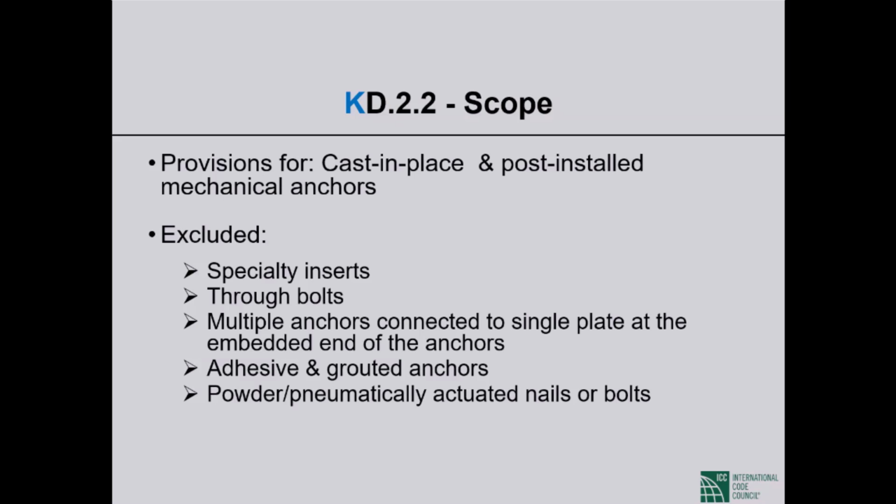However, the problem is the concrete at the interface of the plate, the concrete just above the plate, is of poorer quality. We know that, but we do not have a handle on how much poorer the quality of that concrete is.